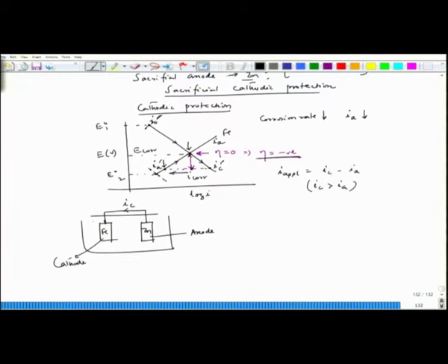of galvanic corrosion, this becomes positive terminal, this becomes negative terminal. So, the current, which is I, flows opposite to the electron flow. So, IC is going this way, it means electrons are coming from this end to this end, electron flow, and once electrons come here, these electrons will be consumed for cathodic reaction.